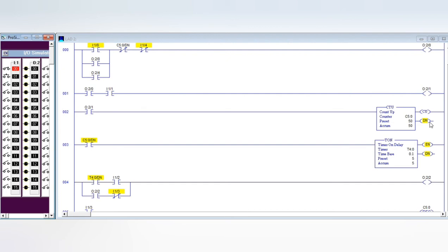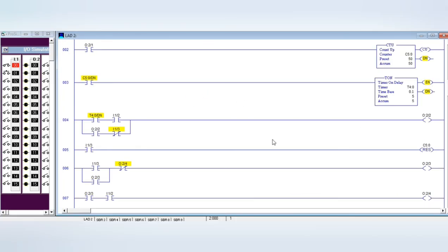Right after this happens, the entrance gate will start to close, and all the cans go through the tube into the compression compartment. What happens next is that this timer, which we set to 5 seconds, will make the cylinder work 5 seconds after the timer is on, and then the cylinder extends. After the cylinder extends, it crushes all the cans into cubic form, right? And naturally it goes back for its retraction, which activates switch I13.